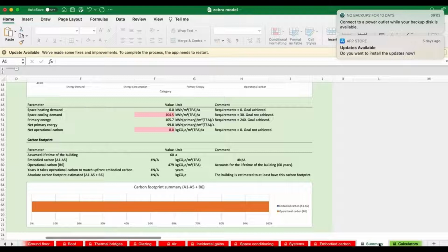So we've now got this building using 104.5 kilowatt hours per meter squared of cooling demand. Obviously, the actual electrical consumption will be half of that, because we've still got a COP of 2. So what strategies could we use to get that number down and actually make these robust against an increase in wealth, but also better designed so that people with not the greatest income can afford to cool them to maybe levels that they might like to see?